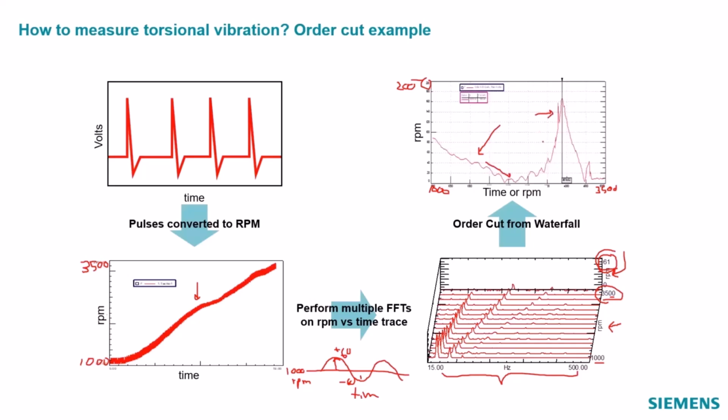What do you think happened there? Looks like we hit some type of resonance. Yeah, so that picture I had earlier of that shaft that's twisting, that might be a thing where a rotating system has a resonance, and so instead of smaller fluctuations in RPM, we get bigger fluctuations. And so something like this, we'd have to address the resonance. Something like this, if we wanted to decrease it, we might design it with more hydraulic vane compartments or more cylinders, or try and make the speed up and slow down between events be less severe.